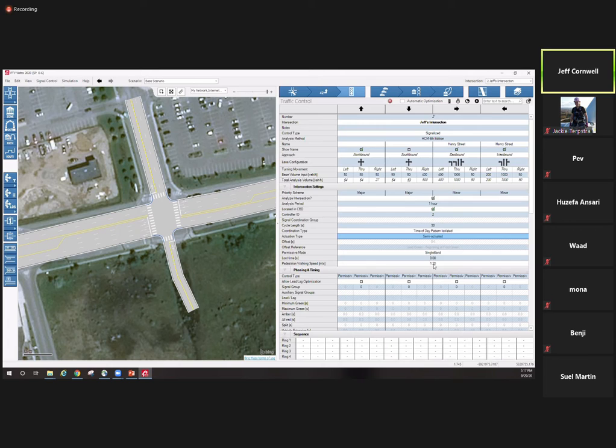And for anyone who's wondering about the pedestrian walking speed, I've noticed that Vistro actually calculates the ped flash and walk time by itself. As you add more lanes, I think it assumes based on the lane width how long the ped crossing is, and then it makes adjustments. But if you know that data, you just want to override it. You can also change this to 1 if you want to have it calculate them based on 1 meter per second. So just something to know, but not something you need to use.